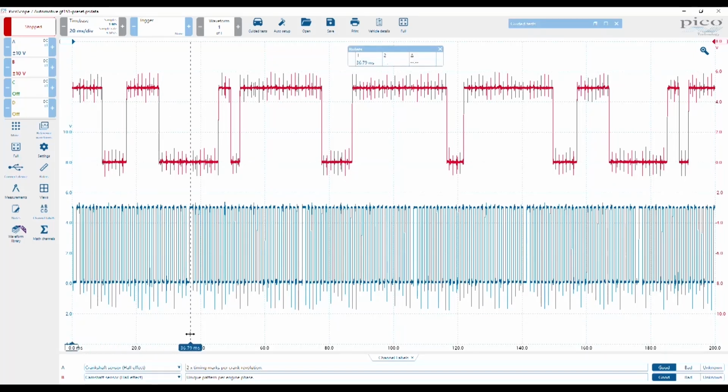So we take one of these points as a reference, so we bring our rulers across for the crankshaft. And then on the camshaft, we're going to look again for a point of reference. Now it's not quite so obvious as it is with the crankshaft what the repetition is, but I promise you it will repeat. So what we try and look out for is a pattern.